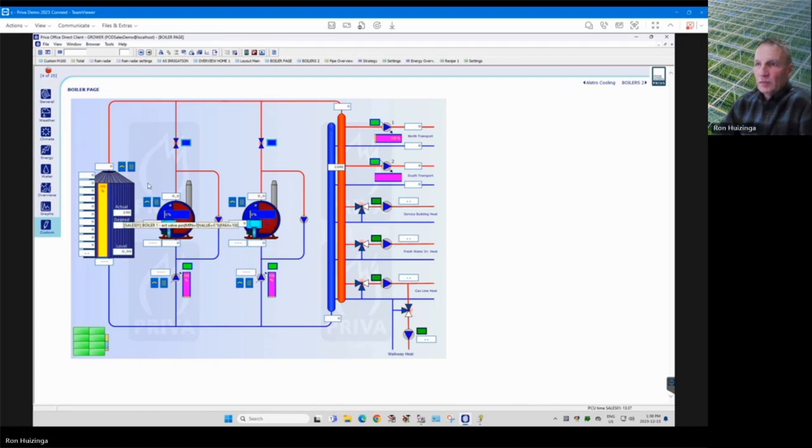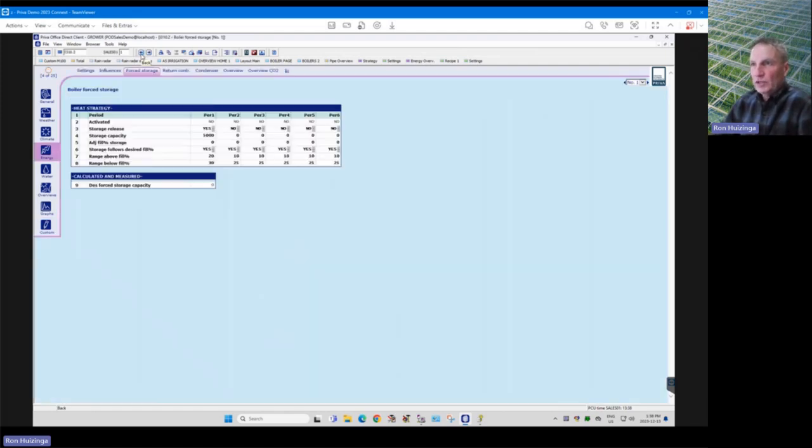So the buffer tank drops down, say in the spring and the fall, to its 20% minimum. And then the boiler is hardly running that day because it only fills up to 40%. So now you're going into the night with the tank only 40% full, and you have a cooler night coming up. So what customers will do is they'll use a forced storage.